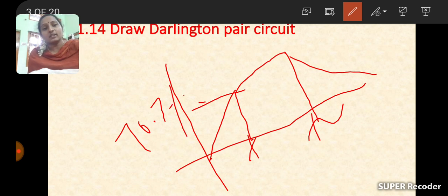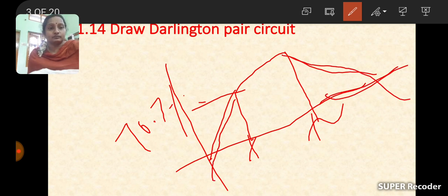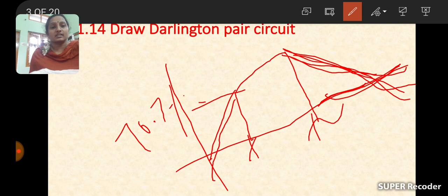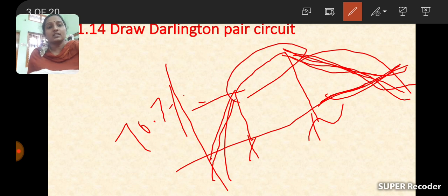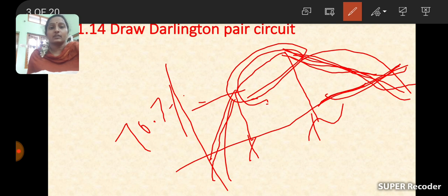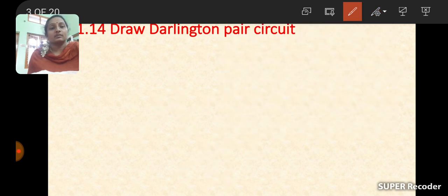At low frequencies and at high frequencies, the gain is reduced. This happens because capacitive elements provide a different reactance to high and low frequency signals, so the gain is reduced. Below and above the 70.7% of maximum gain points, the gain falls. This is the frequency response of the RC coupled amplifier.